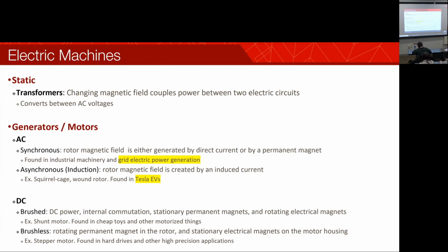It's cordless, so DC, because it's running off a battery. Up until about 5 years ago, pretty much all little motors were brushed motors. But the top of the line ones now use top of the line lithium ion batteries and brushless motors, and I'll show you in a second why that's an important thing. But again, don't worry about the details too much.